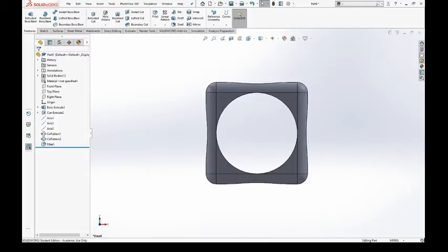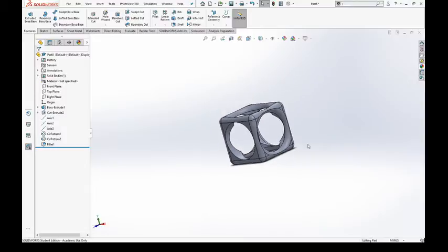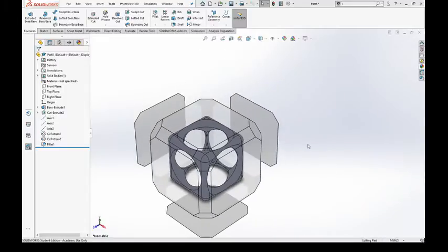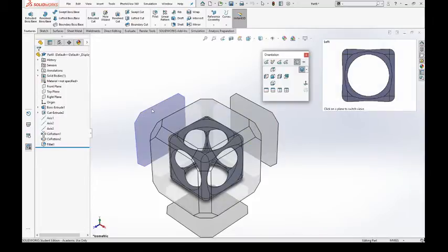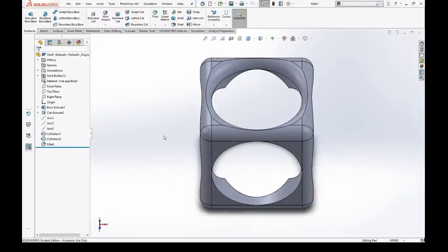You can also use something what's known as the view cube. This is what I use quite a lot. So let me just press control 7 just to get that isometric view, and then I can press the spacebar key. Now the spacebar key allows me to look at this, which is known as a view cube. I can use this to look at a particular section, so I could choose to pick this and it would look from that view.